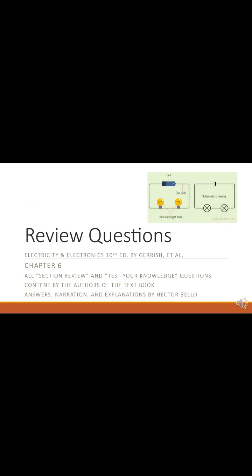Review questions, chapter 6. What does a voltage regulator do for the lights in an airfield lighting system? It keeps the voltage total as required to keep the same current in all lamps, thus the same level of brightness. How much voltage will be found across a good fuse? No voltage or no voltage drop, since there is no potential difference between one end and the other end of the fuse. How much voltage will be found across a blown fuse? Total voltage or source voltage drop. A blown fuse is like an open switch showing total potential difference.